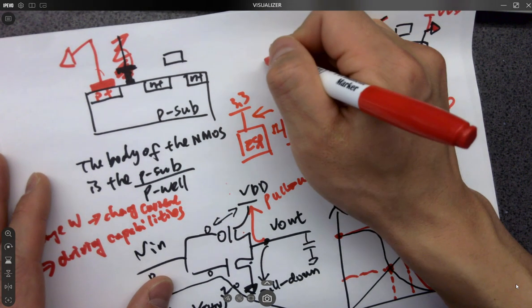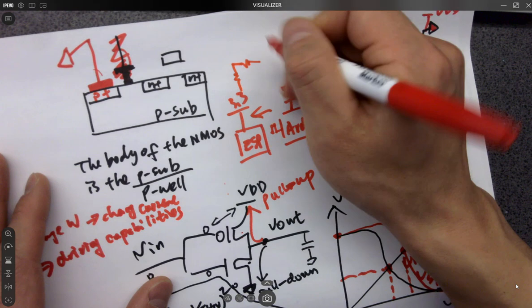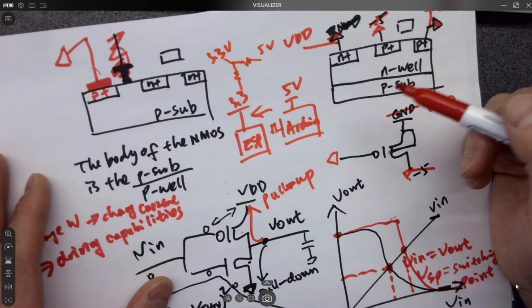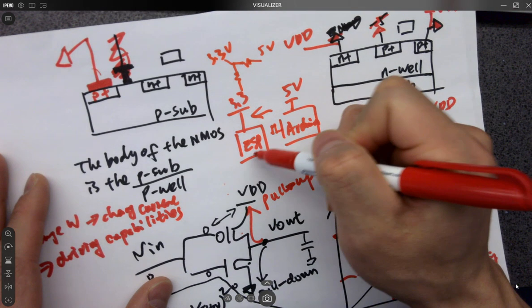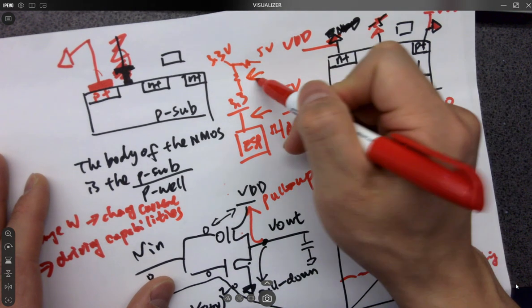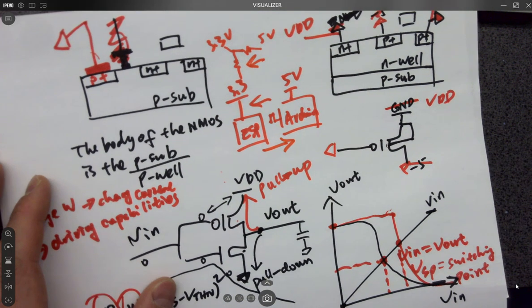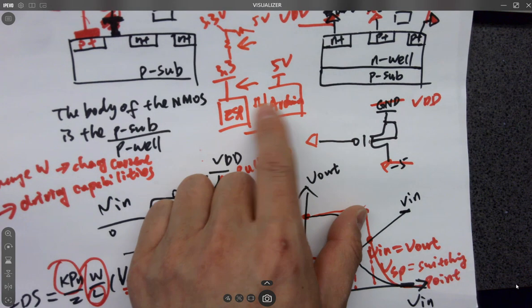Okay, you have to divide it. How do you divide it? You have to use a resistor string like this. So here's a 5 volts logic, and you're getting a 3.3 volts logic output on the other side, and this one is getting input into the ESP. Okay, so in that direction you have to divide it. But in that direction, do I have to do anything? Do I have to do anything from here to here?